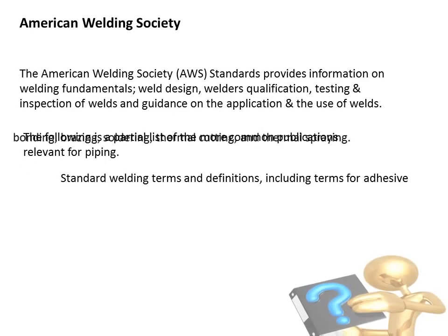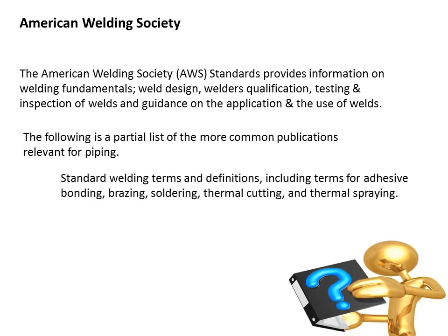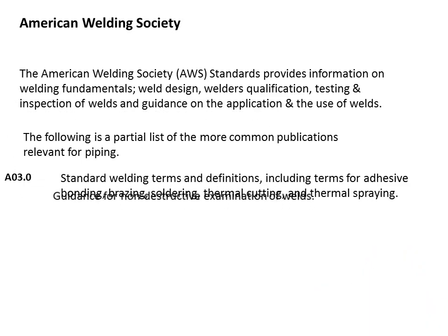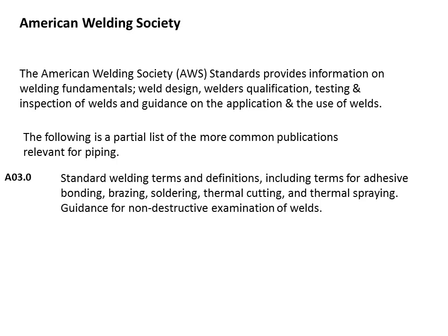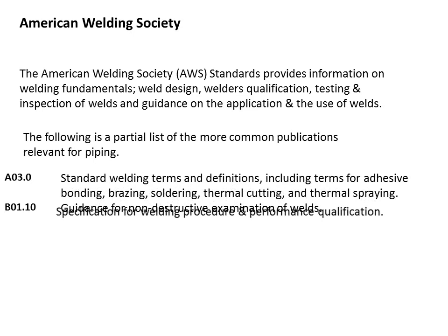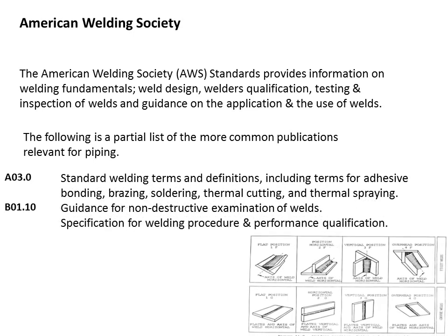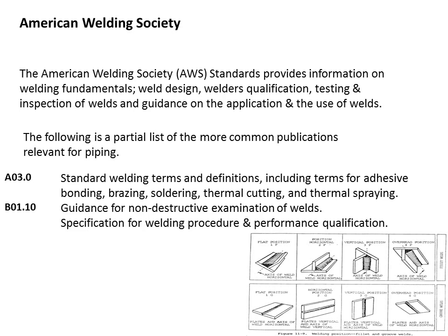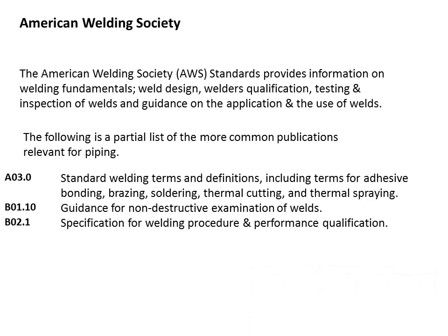Standard welding terms and qualifications, including terms for adhesive bonding, brazing, soldering, thermal cutting, and thermal spraying, are there in section A3.0. Guidance for the non-destructive examination of welds is covered in B1.10. Specifications for welding procedures and performance qualifications are contained in the B2.1 standard.